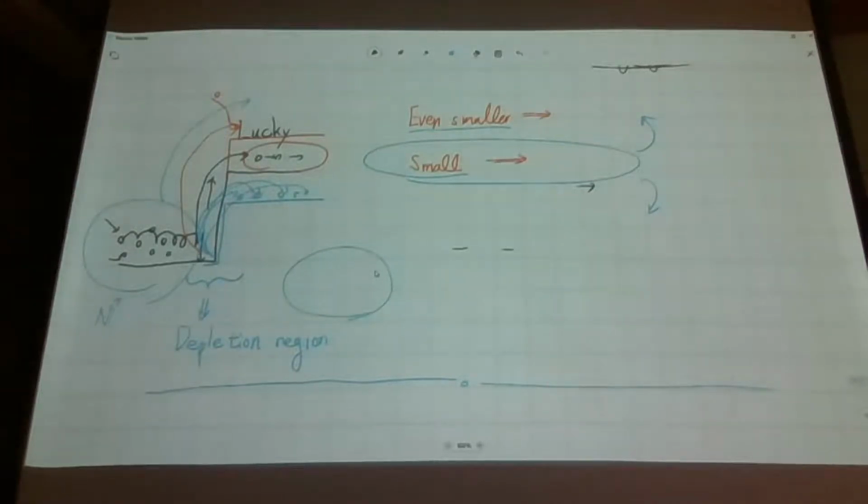All of our discussion up to now was focused on the physical origin of non-linearity. Why does our p-n junction behave differently when we apply forward bias and reverse bias? The short answer, in my opinion, is that internally, even when we apply just 0 volt difference between our two terminals, it has its own structure, which prevents the diffusion of electrons and the diffusion of holes.